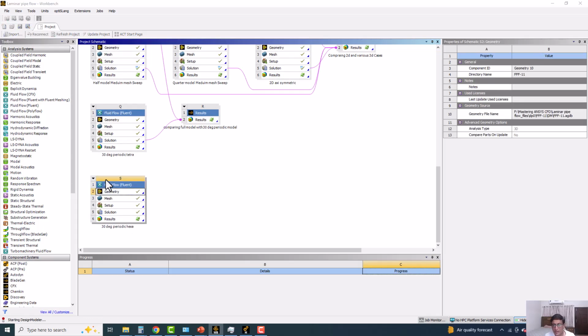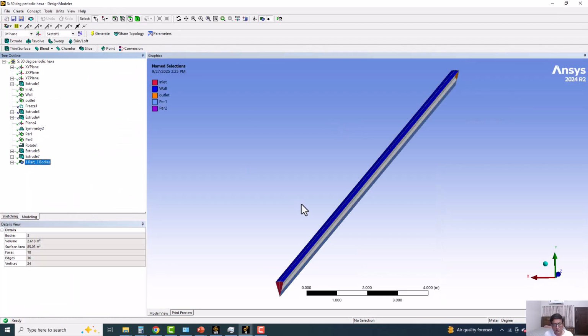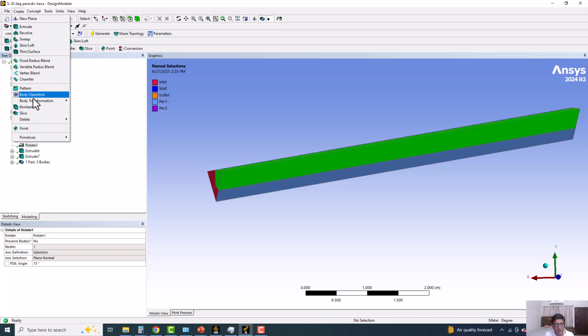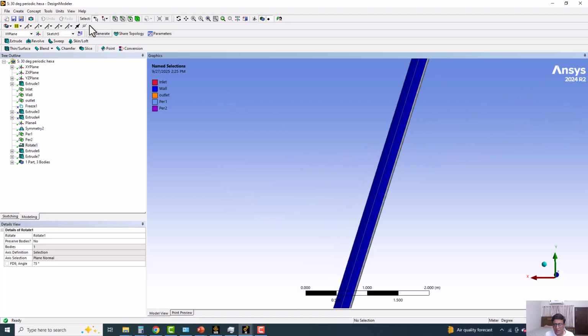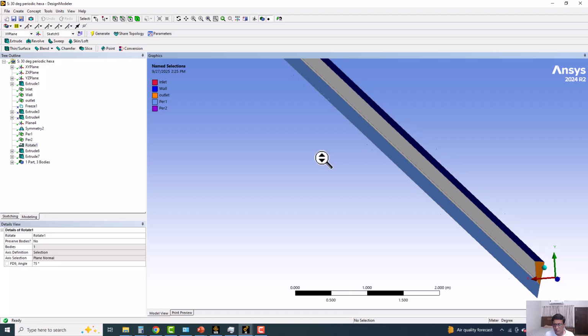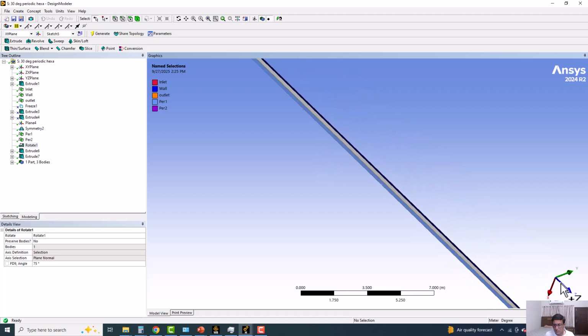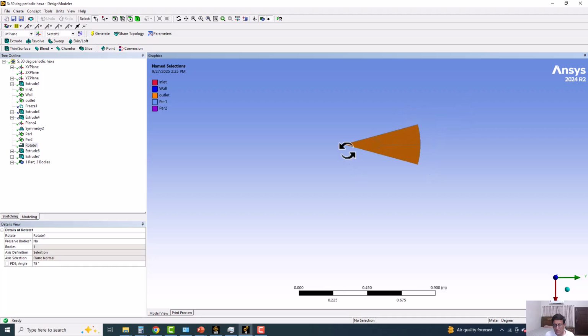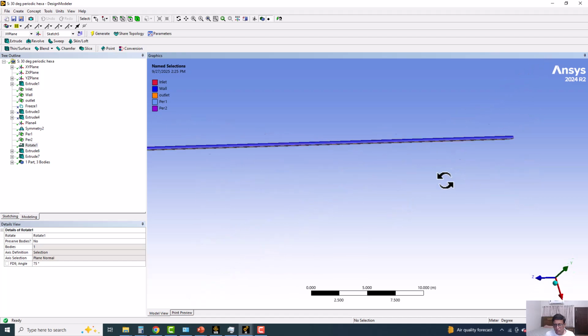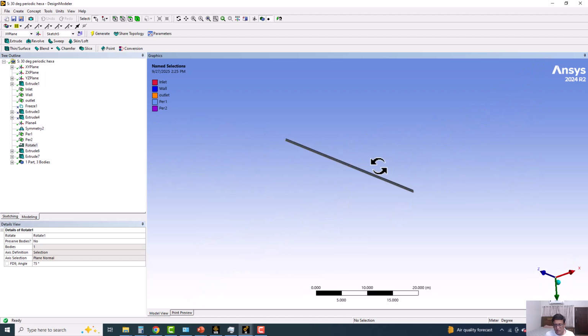Okay, I will give you a brief idea about the geometry creation here. The geometry creation requires some decomposition, so I have to decompose the geometry. You can see here, number one thing is that I clicked on rotate, and I actually put the rotate command, body transformation and rotate. So what I did is that initially the plane we were cutting here was along the x-axis.